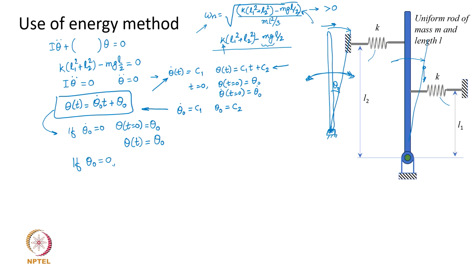of giving any angular displacement to it initially, if I perturb it by giving some initial angular velocity, theta naught dot, that I just tap it with, then theta t is going to be omega t, which actually means that the subsequent angular displacement of this bar is going to continuously grow with time.